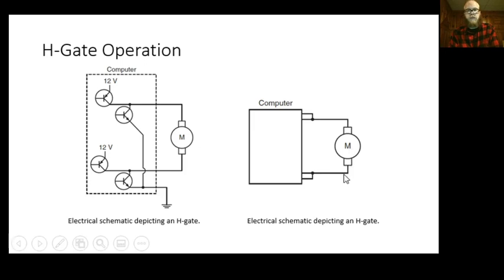Then inside of the door panel, I would check to see, well, let's see if I can just disconnect this connector from the computer, and I'll put power and ground. Did it go up or down? No. Well, maybe that's because it's all the way up or all the way down, so I just tried to roll it all the way up. It's all the way up. I didn't know, so I'll reverse my polarity. So then I put ground and power. Oh, now it moves. I've just proven that my wires are good, my motor's good, and even that my input was good because I had looked at this with a scan tool to see if I was getting the input.